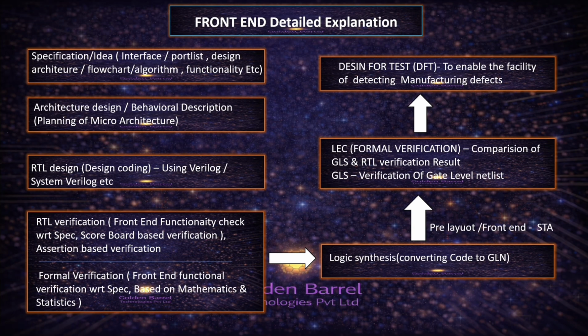Then there is another concept, LEC, logic equivalence check. This is also a formal verification that happens after synthesis. What is LEC? We take the GLS verification result and the RTL verification result, and we compare whether both are logically equal or not. That is called logic equivalence check.